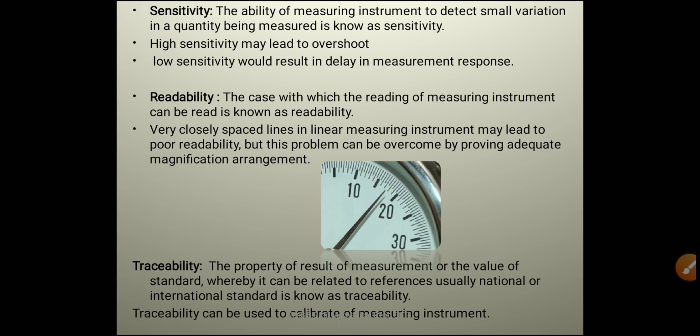Coming to the next characteristic, sensitivity. The ability of a measuring instrument to detect small variation in a quantity being measured is known as sensitivity. High sensitivity may lead to overshoot, and low sensitivity would result in delay in measuring response. So every measuring instrument should be moderately sensitive.